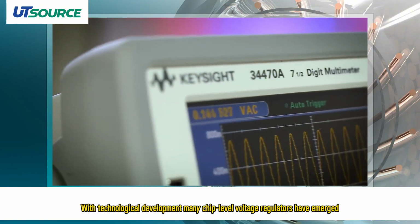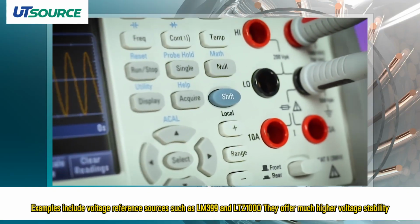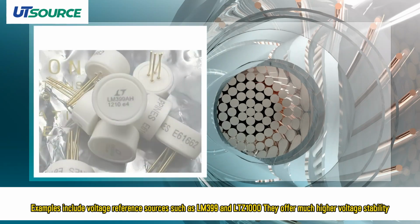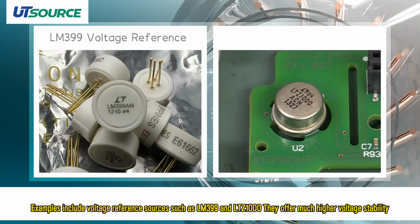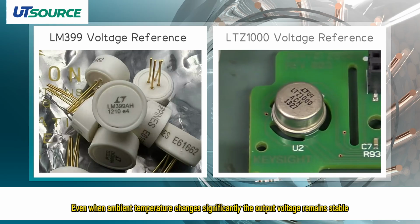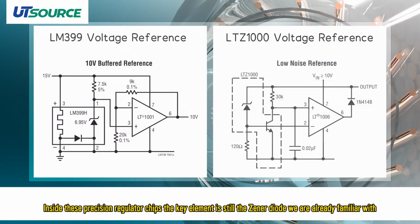With technological development, many chip-level voltage regulators have emerged. Examples include voltage reference sources such as LM399 and LTZ1000. They offer much higher voltage stability. Even when ambient temperature changes significantly, the output voltage remains stable. Inside these precision regulator chips, the key element is still the Zener diode we are already familiar with.